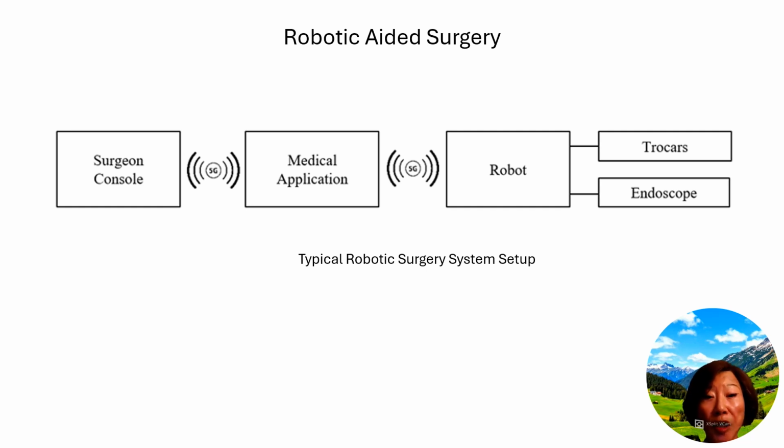Unlike machine-to-machine communication, robotic-aided surgery places a human in the middle of the control loop. This means the console generates new commands based on system state collected in the previous 1 kHz cycle and the surgeon's hand movements. Each piece of equipment in a robotic telesurgery setup, for example endoscopes, image processing systems, displays, motion controllers, and haptic feedback systems, needs to be synchronized using a common clock, either external or provided by the 5G system.